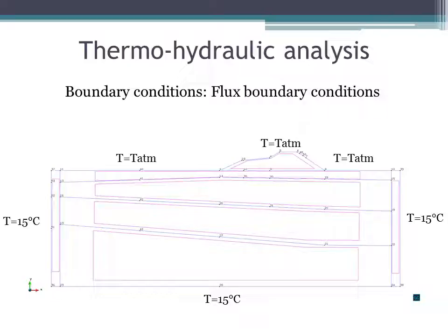In order to make the thermohydraulic analysis, the temperature has to be assigned on the boundaries. Under the filled surface, the temperature has been imposed to 15 degrees. On the filled surface instead, the atmospheric temperature measured in situ has been applied. It has to be noted that at first the evaporation was applied as a flux, so the atmospheric module of CodeBright was not used.